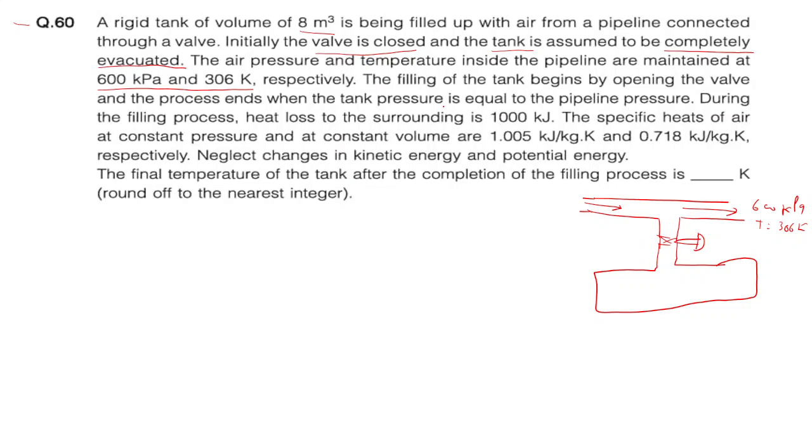Keep this in mind. Filling up of the tank begins by opening the valve, and the process ends when the tank pressure is equal to the pipeline pressure. Because pressure here is less, when it opens air will come in suddenly, but when pressure becomes the same as the pipeline, it will stop, right? And we will close the valve.